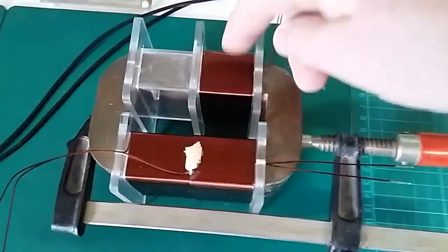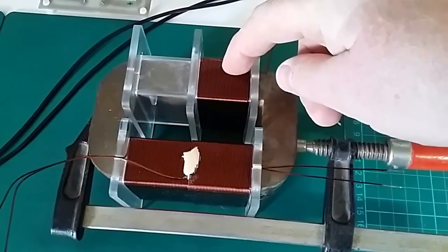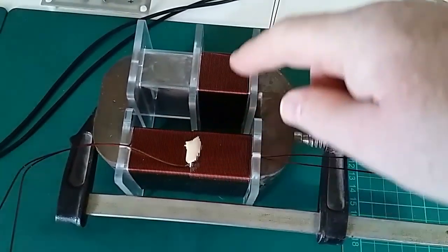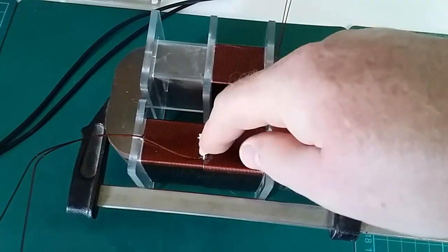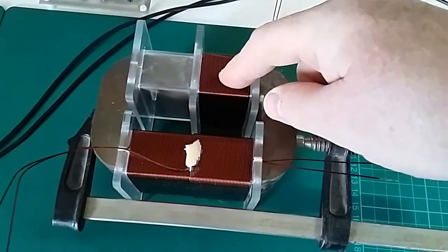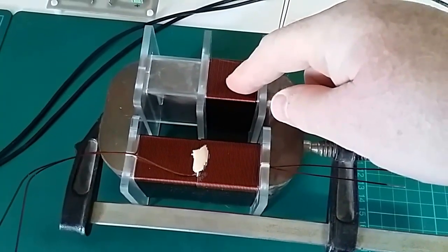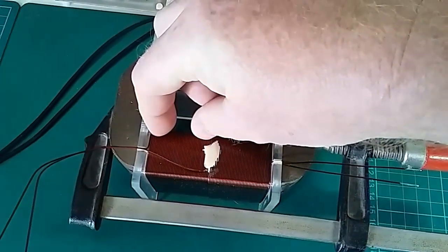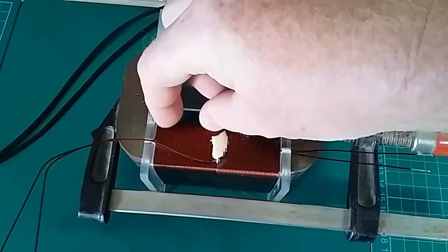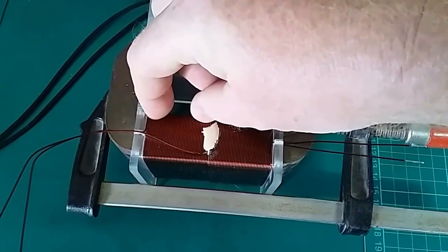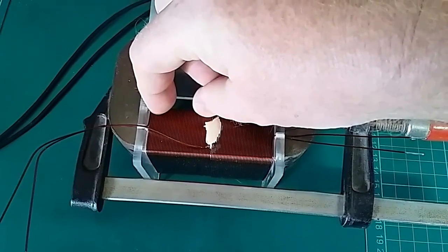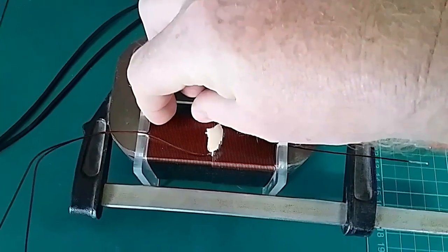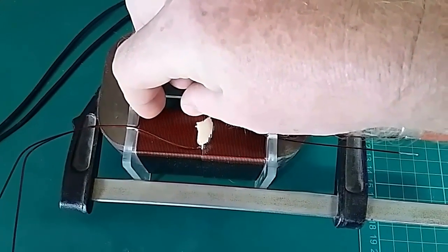Now I just want to point something out while I'm here. This coil here is going to be my input coil. This coil over here is my experimental coil. This will be driving this coil over here. So inductively, if you think about this, this coil over here is only going to work on this portion here, induce an EMF. Remembering an EMF is a voltage, the current changing in this coil is going to induce a voltage in this part of the coil only.